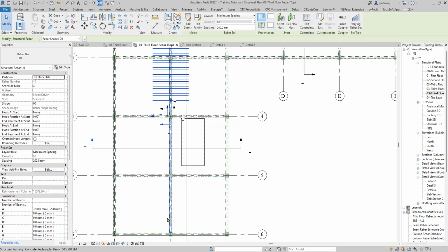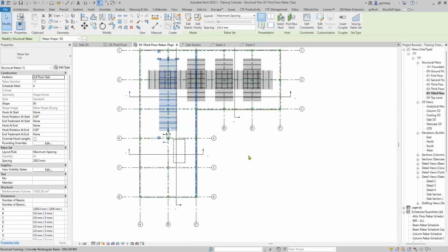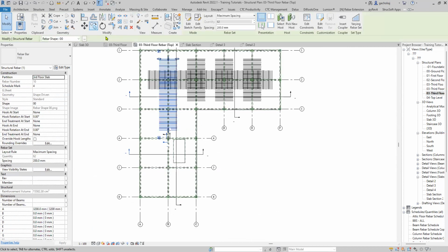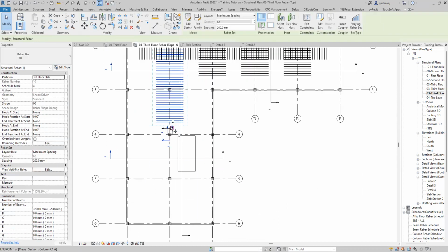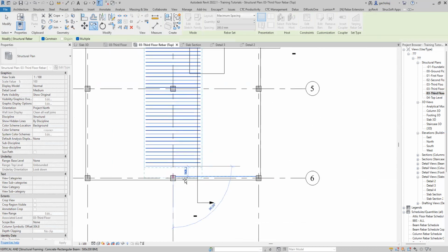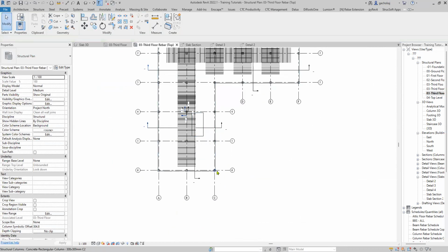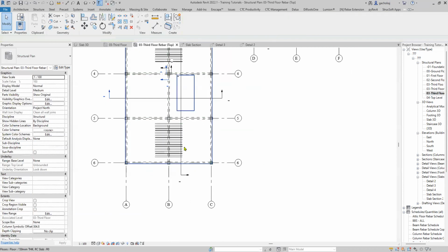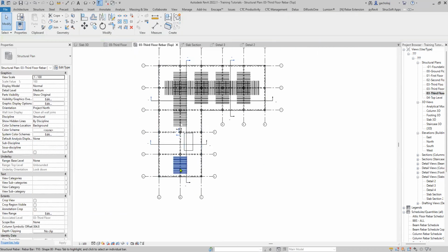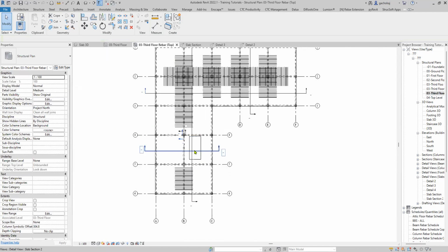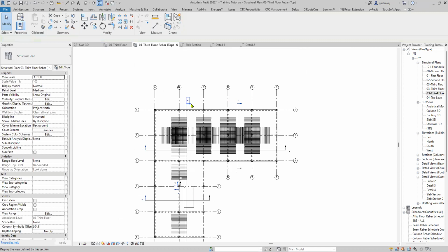I know I still need some tops here. And instead of redrawing, as I said, I'll just copy this. Select this, use copy. And just copy this down here. Escape twice on your keyboard. Then select and stretch these downwards. I'm not sure where, but we'll use this section to confirm the exact length, the exact span, of these top ones. So I'll just open this section again.